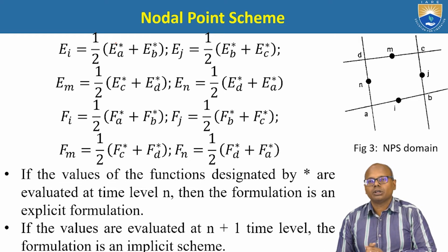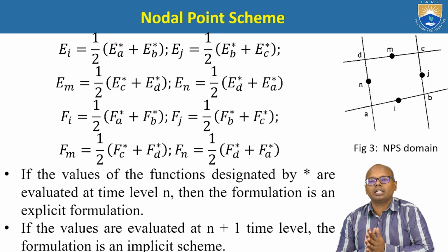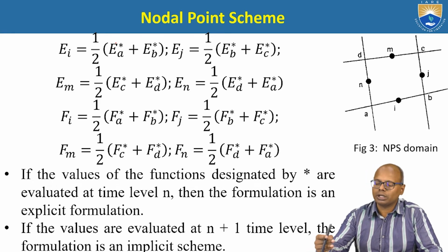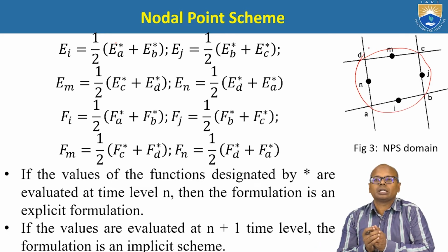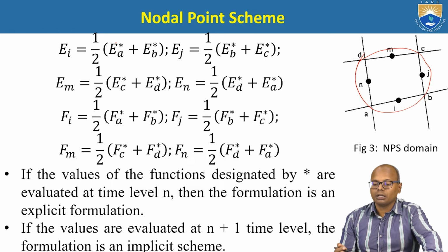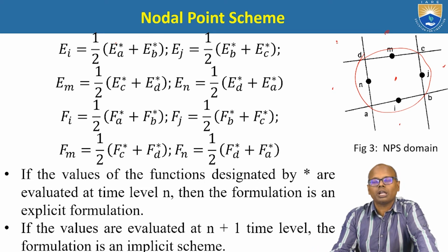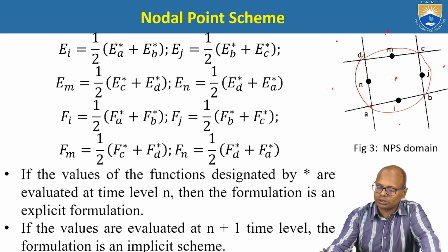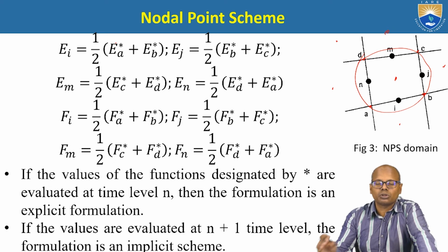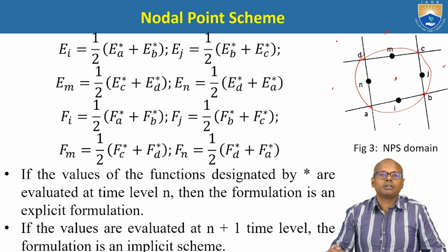A conclusion for this class. In this class we have seen that we take the quadrilateral element and integrate the governing equation over this quadrilateral, and we use the cell-centered approach or the nodal point approach to transform that into the algebraic equation for further calculation. If it is a cell-centered approach, I take the node point in the center of each cell. If it is a nodal point approach or nodal point scheme, I take the vertices of the quadrilateral as the nodes. That is the only difference between the cell-centered approach and the nodal point approach, which are the basic methods for applying the finite volume method for solving any fluid flow or heat flow problems.